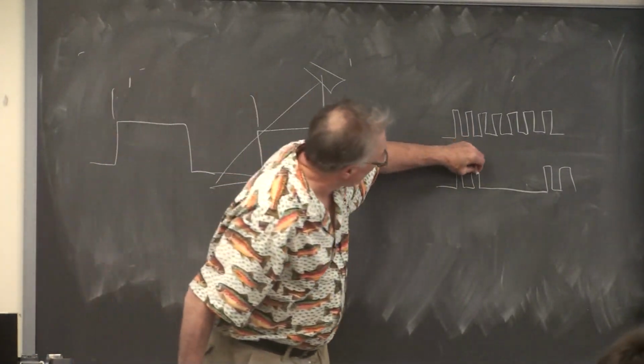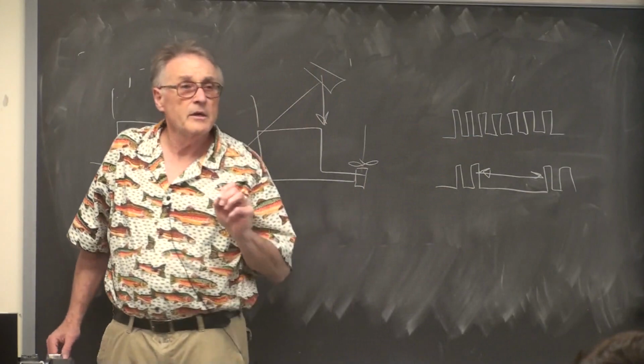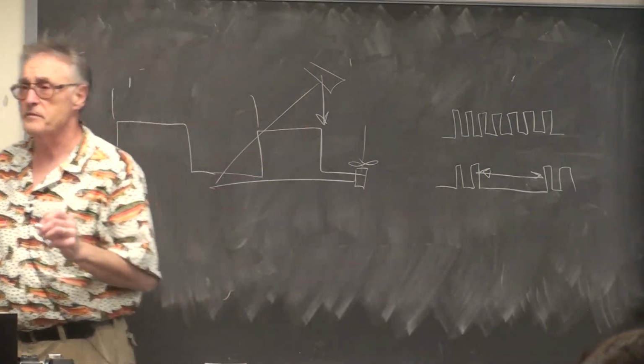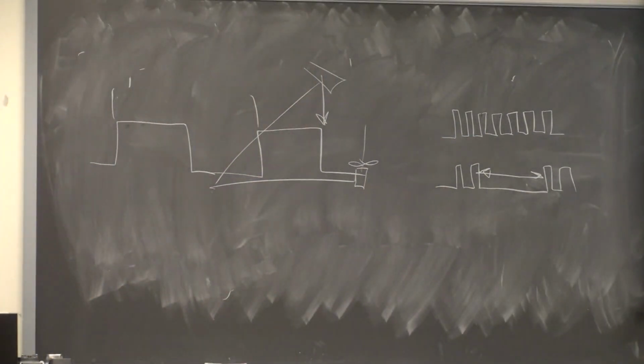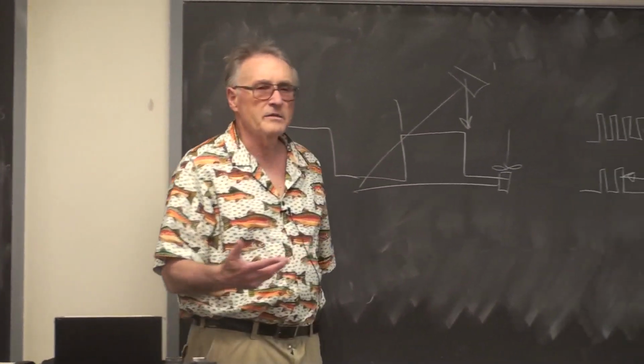So if you go from here to here, then you get a pretty good estimate of the total time that the interrupt service routine has taken over the CPU, including exit time and entry time. It's kind of like the shadow left when main can't execute. So any of these methods will work.